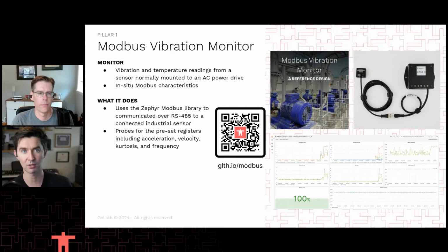And that's what we talk about in one of the videos that you see on that QR code there as well. And you would want to do that because preventative maintenance is kind of the standard way of doing things, like every 6 months, but then you could start to see problems early if there were early problems, so you don't miss it if you're only checking every 6 months. Or if you really want to start to cost optimize, you also could maybe stretch it further until you start to see problems showing up in the data, and then you start to see that as well.